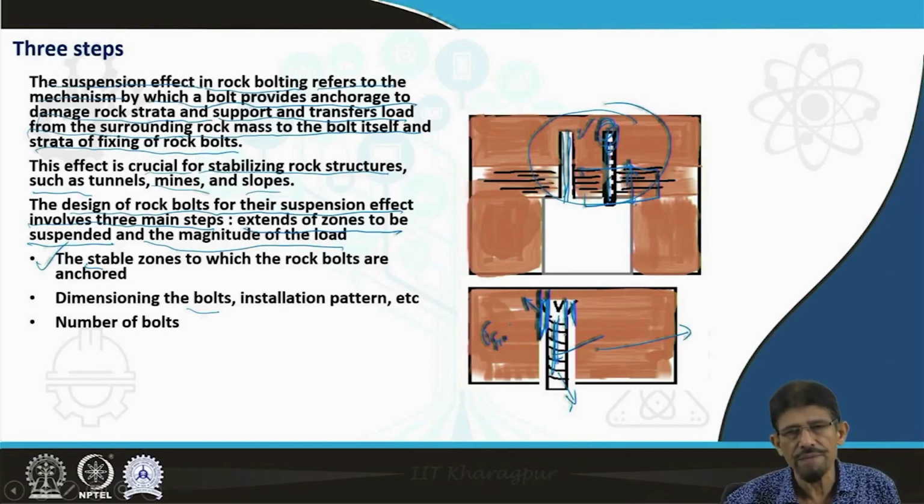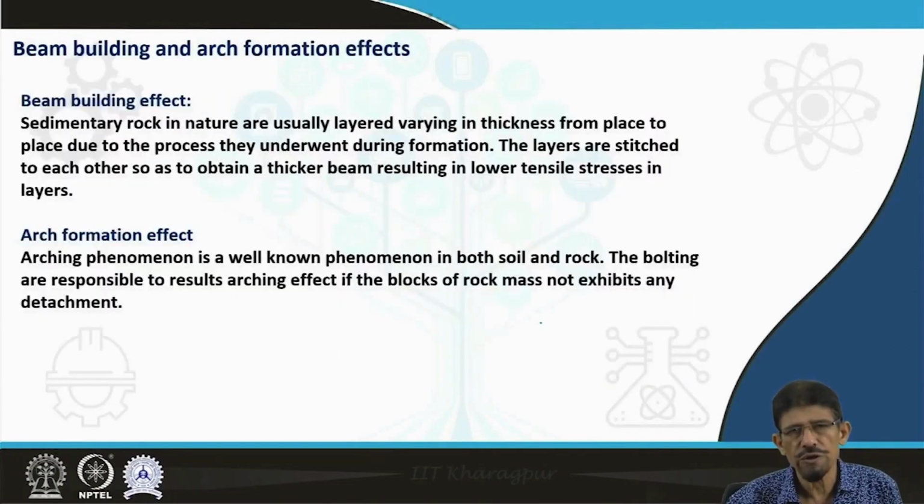And what is the benefit of this mechanically anchored rock bolt? That can be utilized further and further. However, the grout anchored rock bolt cannot be utilized further due to permanent closing of this. Therefore, we leave the tube bolts inside.